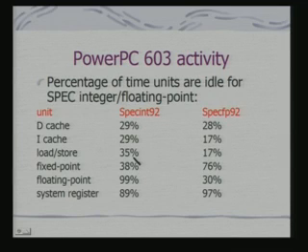Now, you will also see these caches, the data cache and this instruction cache, which we have already seen in the context of Harvard architectures. They are also not always used. So, about 30% of the time, in case of this kind of benchmark, it is unused. So, here also the issue comes up how you can effectively organize this cache so that you can minimize this kind of energy consumption.